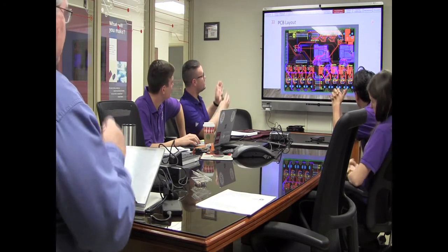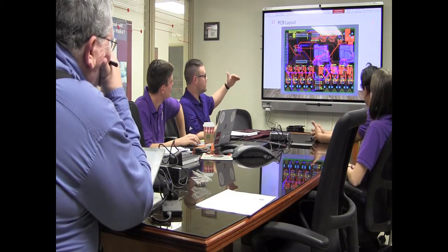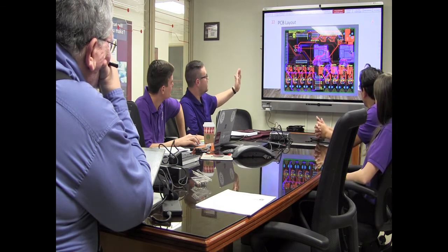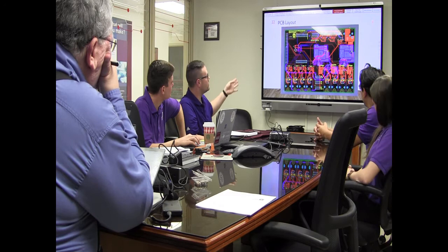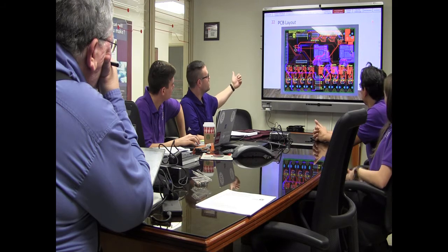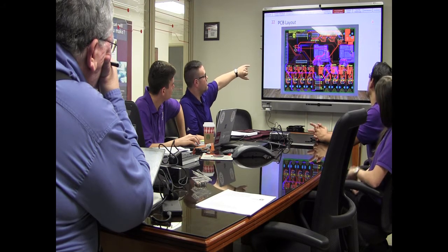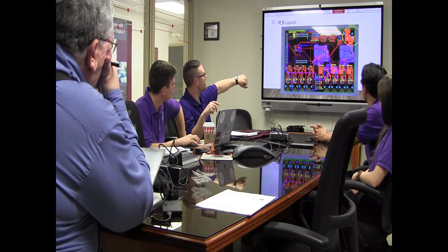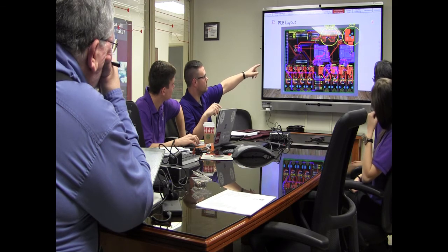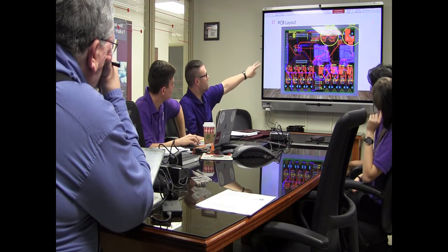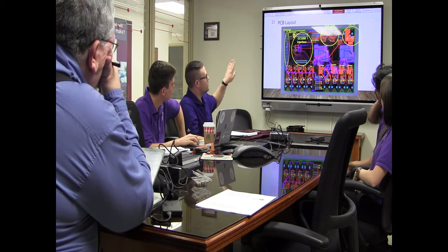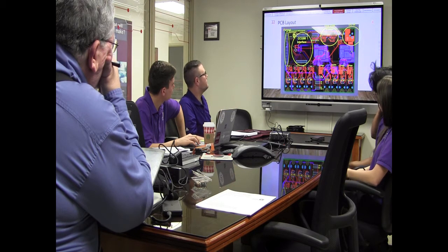So it's 6 inches wide by 4 inches the opposite direction. It's set up with the 40-pin IDE fan out all the way to the left underneath the board, as well as a PCA9685 PWM generator, also on the back side of the board. And then you can see on the left-hand side, actually if you pull once or twice, you can see DC in, coming in from our wall jack with nice big connection planes, dual USB power out, the CC3200 launchpad interface that's above and below the board, so you can stack as many as you like.